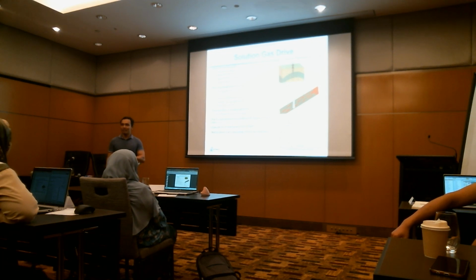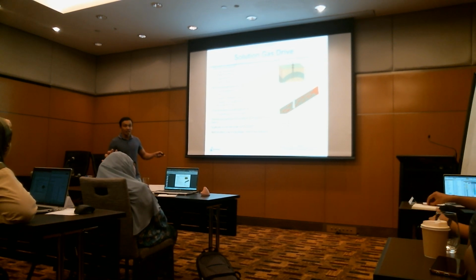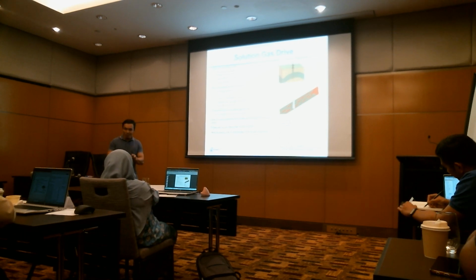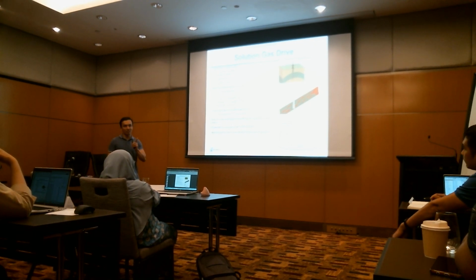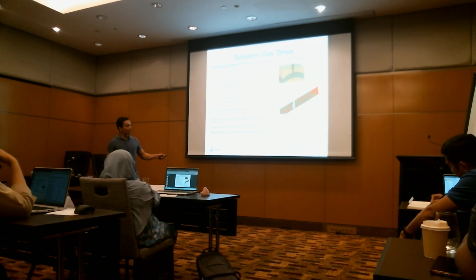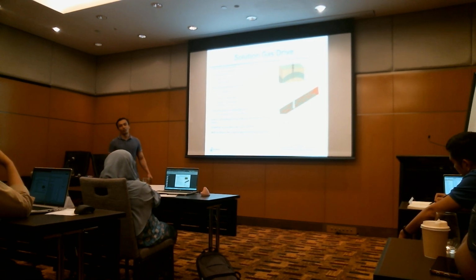We are talking about the critical gas situation. Okay, now what happened here? Gas is already there. Gas has already come out from the solution. But just imagine it's not a lot. It doesn't reach the critical gas saturation for the gas to move. Gas is there, it's liberated but not moving yet. So that's why it's slumping. Once it has reached the critical gas pressure, then it starts to move.